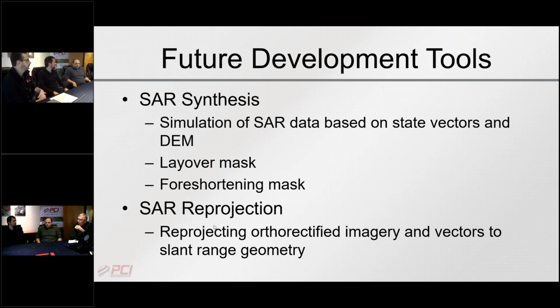That's the converse of that. That's the way I generally use it: I generally look for areas that are below a certain threshold, and then just mask them out automatically, and then put a buffer around it. And you can filter based on the buffers and things like that. And Guy's done a really good job with erosion and dilation effects. So it's a very easy program to run. You can run multiple layers of erosion and dilation in whatever order you want. It's really a very, very powerful tool, and I think this is the first time it's been released. Yeah, and in this release, I really like that tool too.